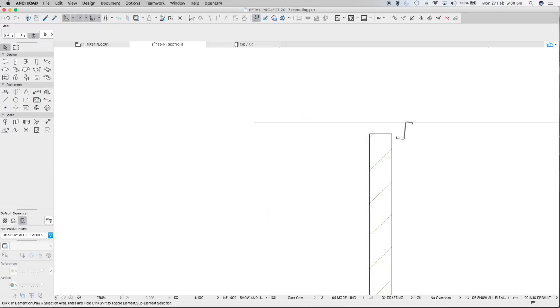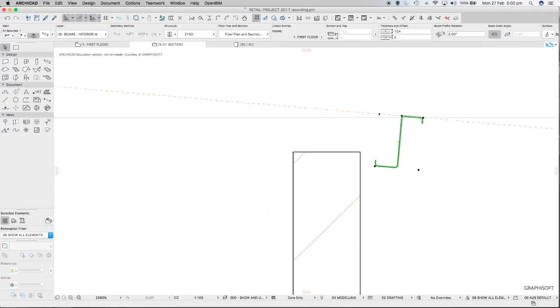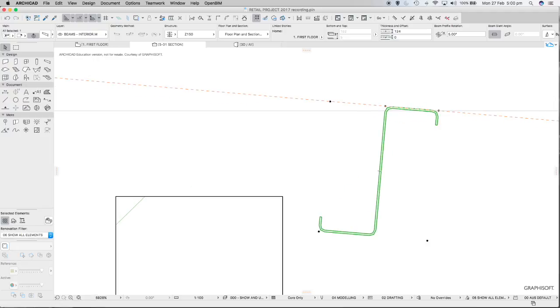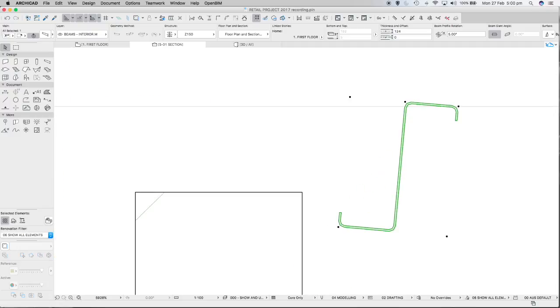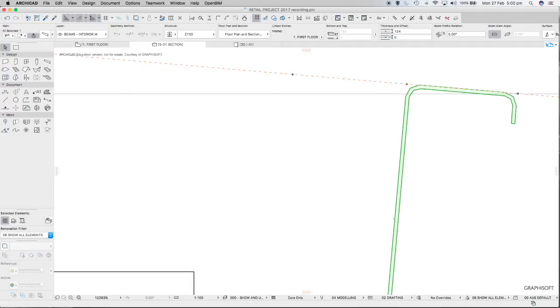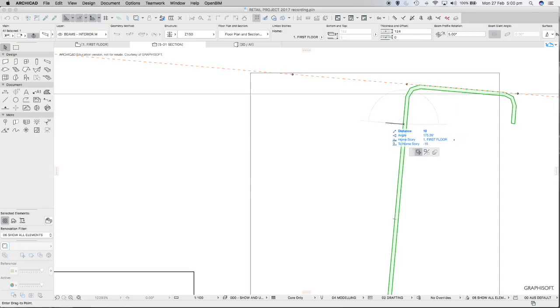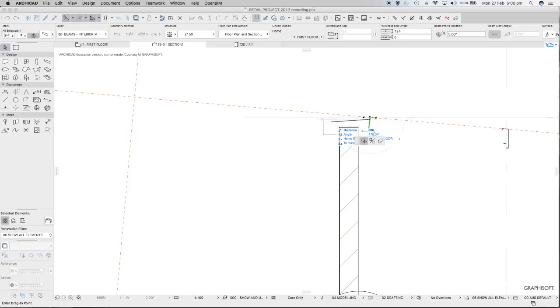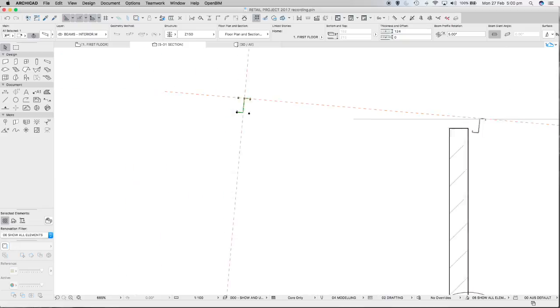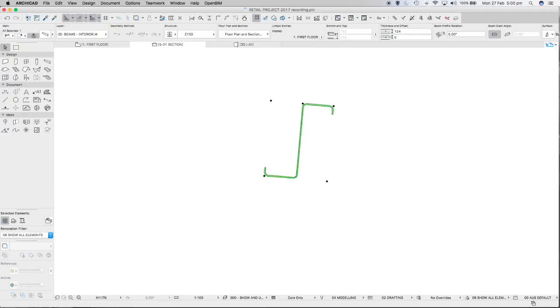and then we can select this purlin, and then select it again to get drag happening, but select it from somewhere like, well, that's where that guideline was from, that left-hand edge of that web member. So select it from somewhere along this edge like I'm doing, and make sure you're in the drag command, and then do the copy, so your control key, option if you're on a Mac, and copy that to this next one. So we've now got another purlin in place.